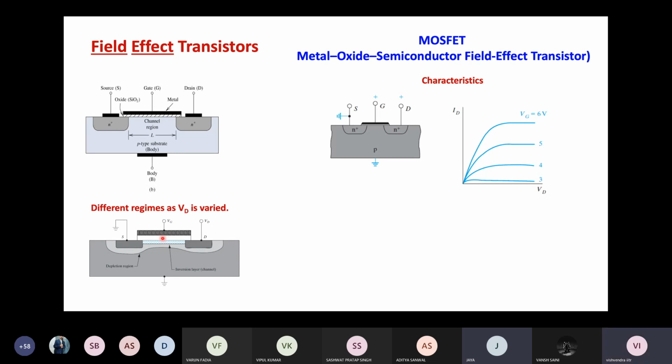If there are lots of states there, if this interface is not clean and the proper lattice matching is not there, there may be interfacial charges. Interfacial charges means that if there is a mismatch on the interface between two solids, some charges might get stuck there, and they can entirely spoil the operation of the MOSFETs.